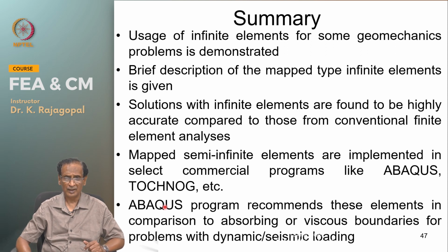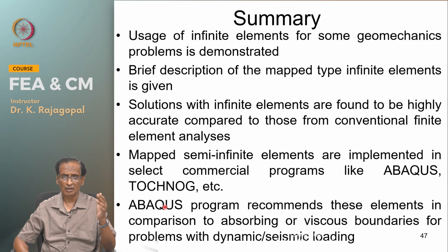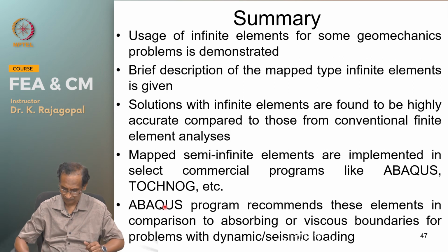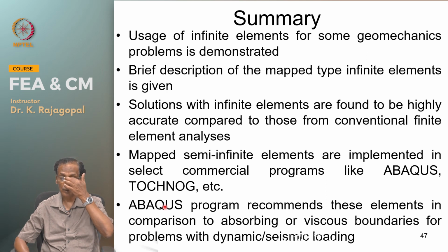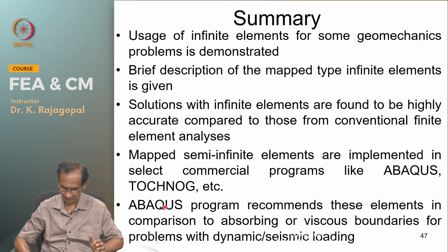And in the Abaqus manual, they recommend the use of infinite elements in place of our viscous boundaries, because they usually give better results. That we will see later. I will show you one example that was obtained with viscous boundary and then with these infinite elements.